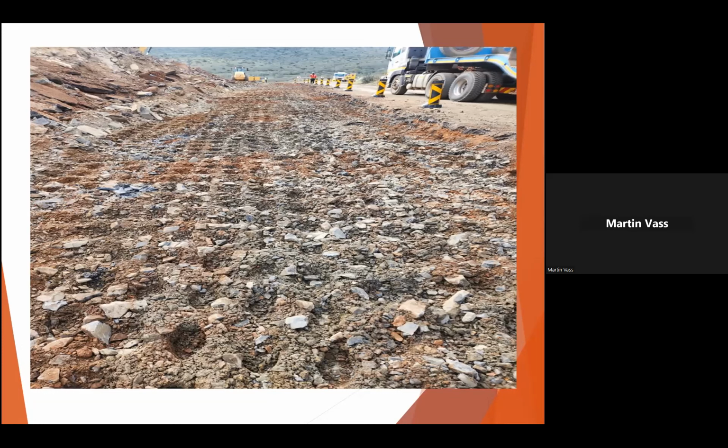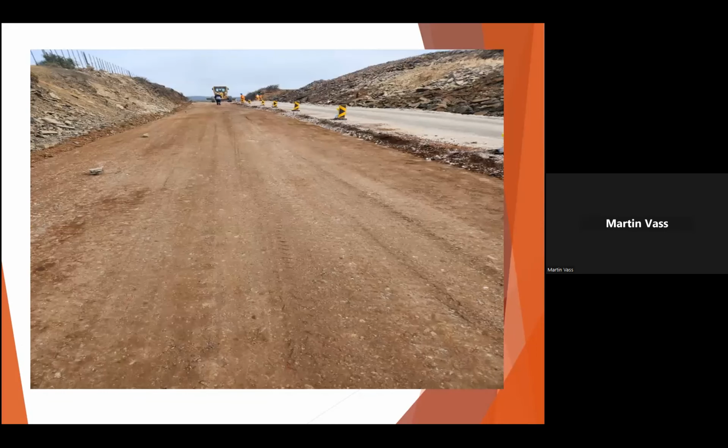So it took some time. There was a lot of disquiet from the locals. We reduced down to 1 lane while we repaired the second lane, and then we repaired the first lane. So it was done in half widths. That's it, just before we're putting the final base course on and the final premix going on.